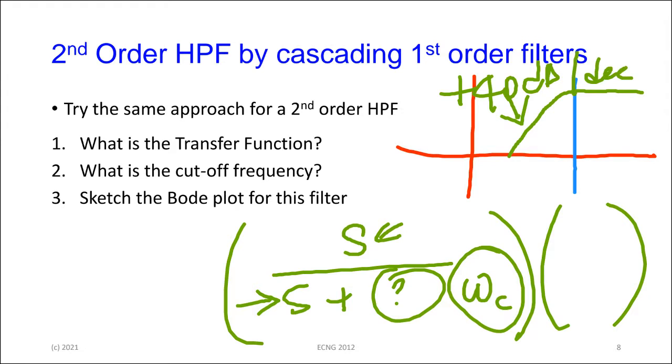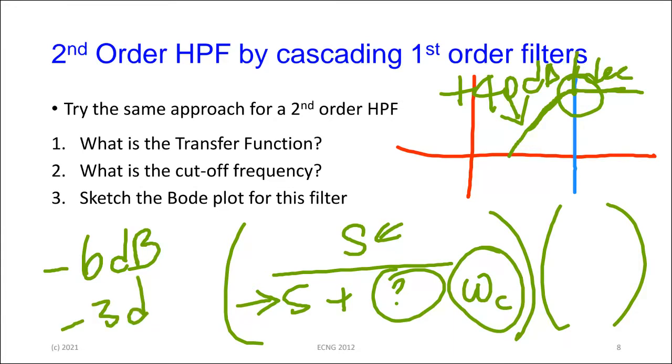So it doesn't pass anything, and it's going to go up here until it reaches the cutoff frequency, right? And like the previous example, at the cutoff frequency, the attenuation at that point is going to be minus 6 dB, right? Whereas for the single op-amp version that we did yesterday, the Sallen-Key version, the attenuation at cutoff is minus 3 dB.